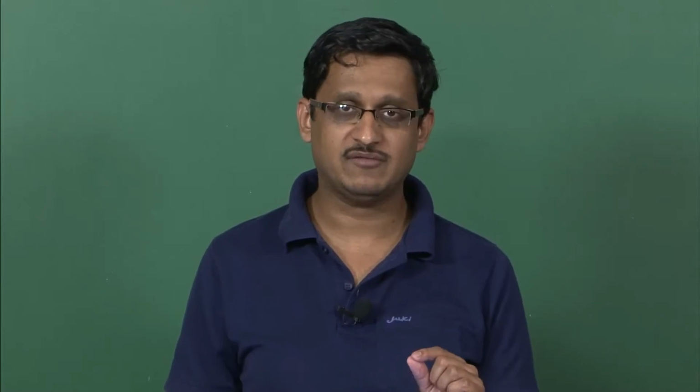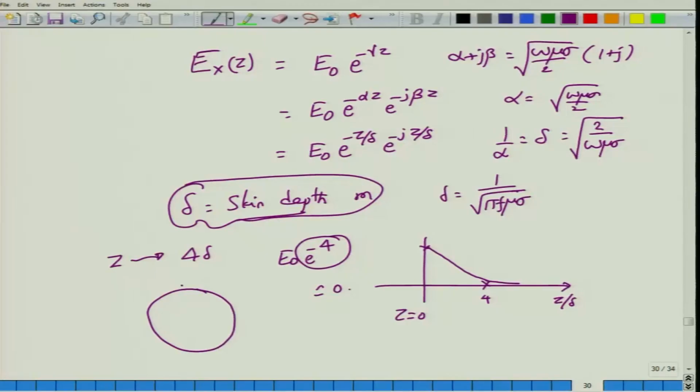That is a very important factor to remember. Skin depth is inversely proportional to f. So, the same medium which might have a very large value of delta for a small value of frequency will have a corresponding value of delta that starts to decrease as the frequency increases. If you consider a solid conductor or wire, the current through this conductor would be uniform at f equal to 0, because the current density, which is proportional to the electric field, will have a skin depth of infinity, which means there is absolutely no attenuation.